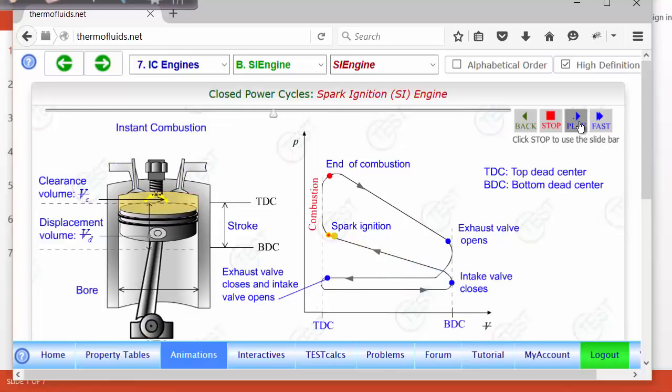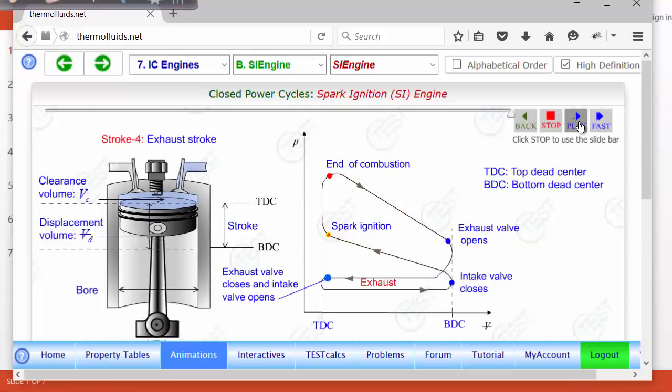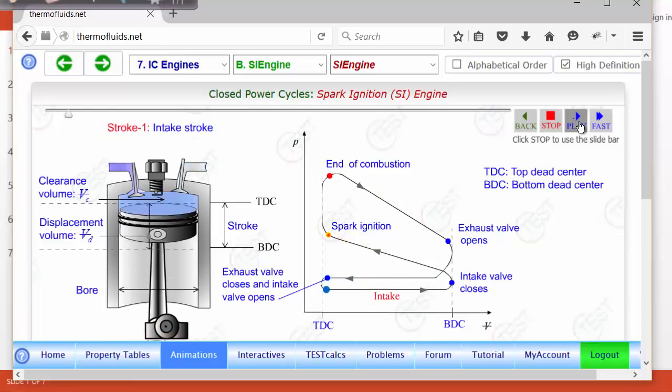It's a very complicated cycle. So we'll go step by step and show how ultimately this complicated cycle really mimics the simple cycle that we just covered, which is a closed system going through a steady state. Already we saw this is not a closed system, as we see the valve opening. Second, it's obviously not steady because the picture is changing with time. The piston is going up and down. So first, let's start by examining each stroke individually. We'll not worry about the analysis at this point, but first let's go over the mechanical part of it.